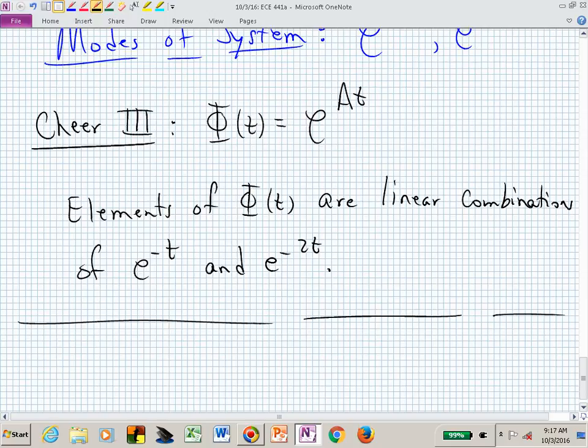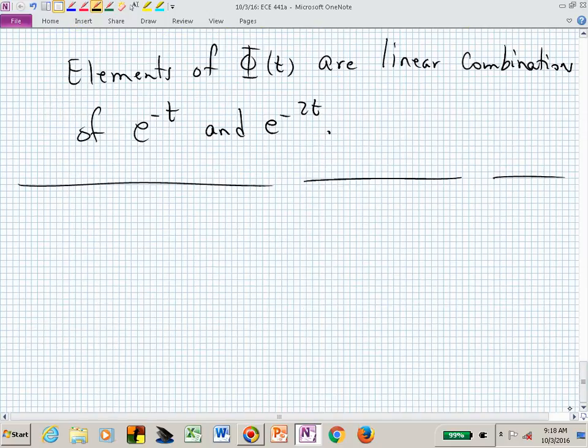Knowing the poles of the transfer function, or knowing the eigenvalues of your system, gives you a lot of insight into the system's behavior. The big one is maybe, is it stable, is it unstable? All you need is one of those to be in the right half plane and your whole system is unstable. If they're stable, now you can start talking about how quickly they are dissipating, or how they are shaking if they have some imaginary part to them. How quickly do they move around, and how quickly do they decay? You now know a lot of information about dynamic systems and how they perform.